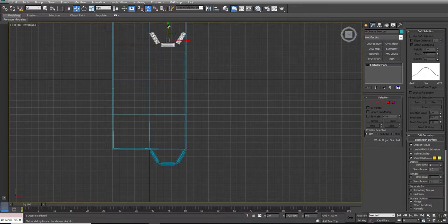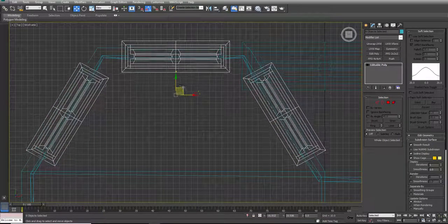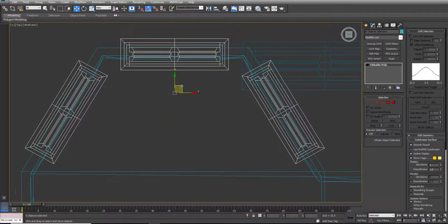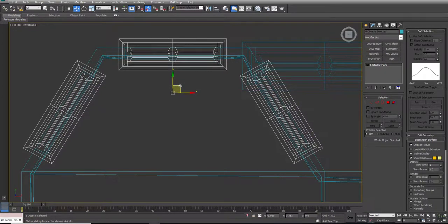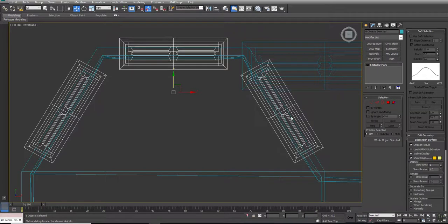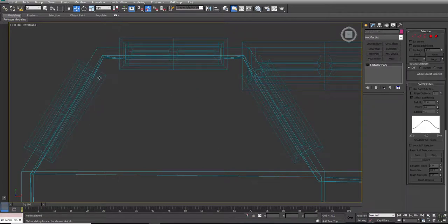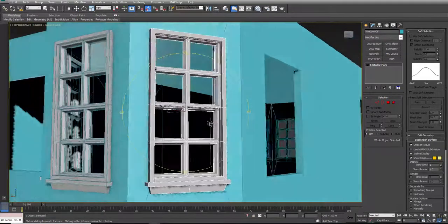I'm going to move them down. Go into rotate. Rotate them 180 degrees. Go into move. Hit Z to zoom in on them. I'm also going to hit G to turn off the grid. Now I'm just going to kind of work to center these again. Alright, so that's about centered. Comparing over here, let's Alt W to go out and then Z to zoom over. Okay, this is looking pretty good.